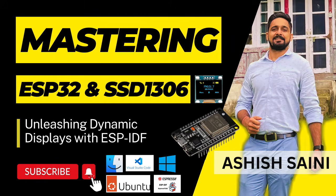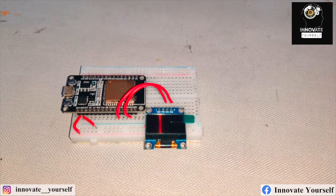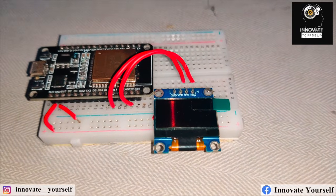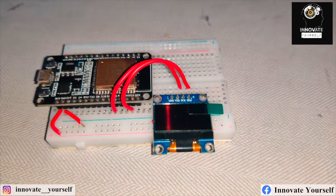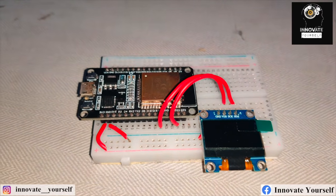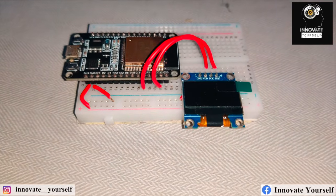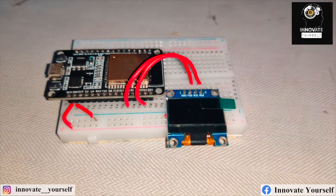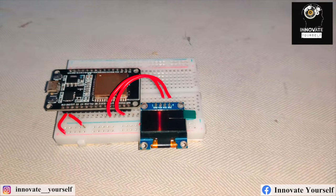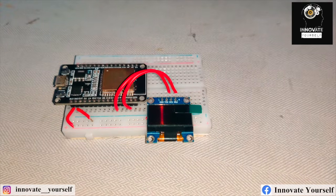Now, let's move ahead and get started with the connections of your ESP32 with the SSD1306 module. So this is the connection of your ESP32 with SSD1306. You can see here we have connected SCK and SDA pins to pin number 22 and pin number 21 of ESP32, and also we have provided a proper ground and VCC so that we can make proper communication and give a proper supply to the SSD1306 module. So this is about the connection.